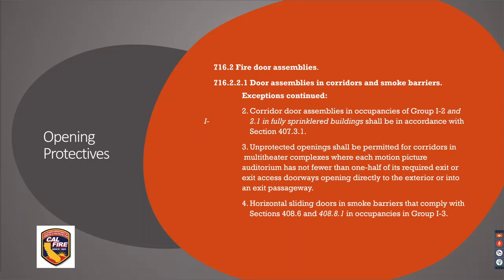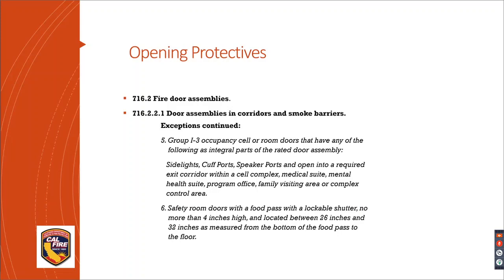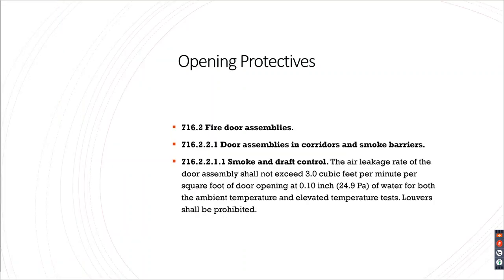And we'll skip the second one. You're not doing theaters. Horizontal sliding doors in smoke barriers that comply with 408.6 and 408.8. Oh, that's an I-3, sorry about that. 5 is about an I-3, and then for 6, talking about safety room doors, that's not for us.